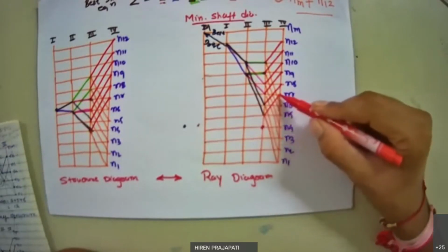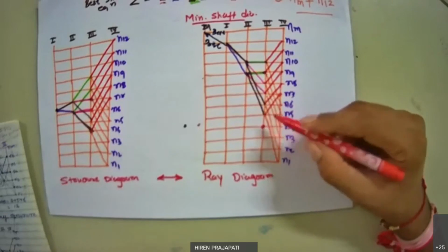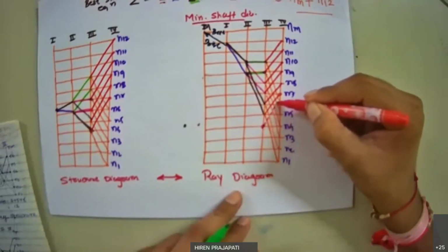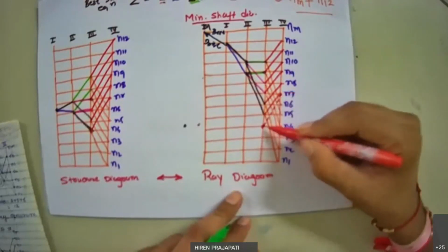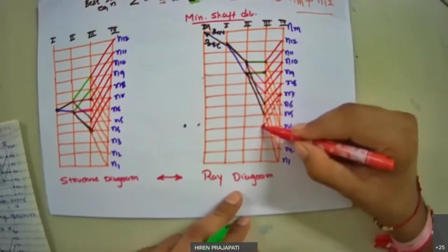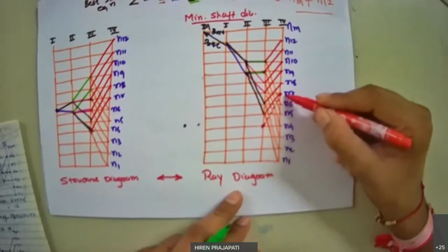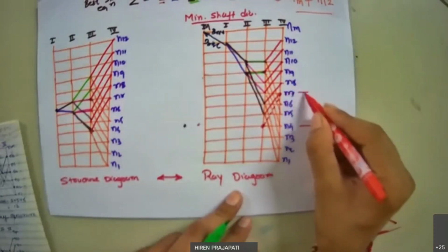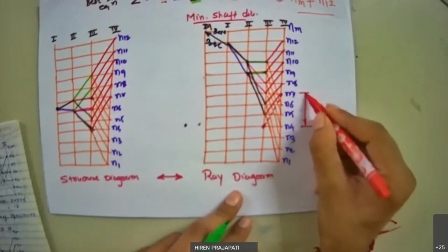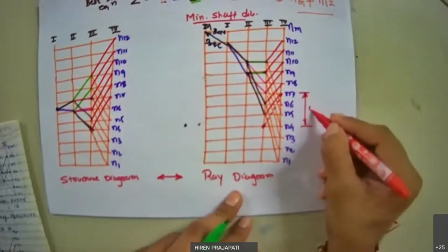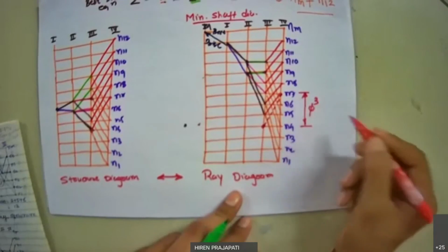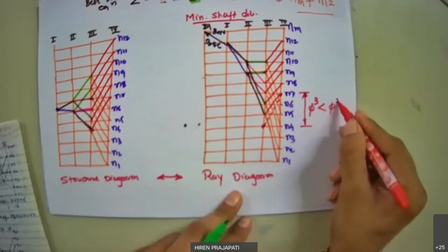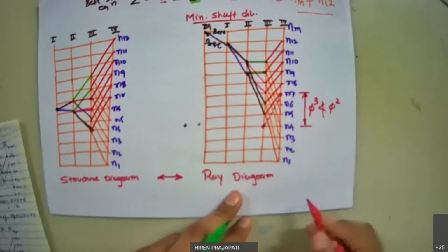This red ray will connect, let me indicate, that will be connected with N7. From this, if I consider N4 as the input speed and as the output if I am getting N7, then how much is the geometric progression in increasing order? It's 5 is to 3, which is violating 5 is to 2 condition, right?